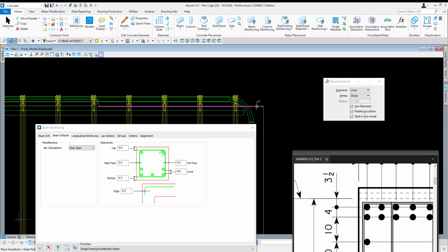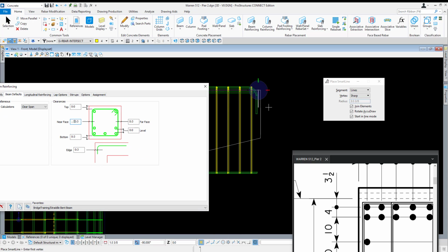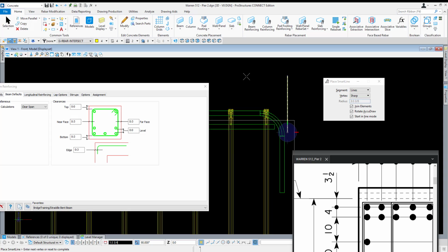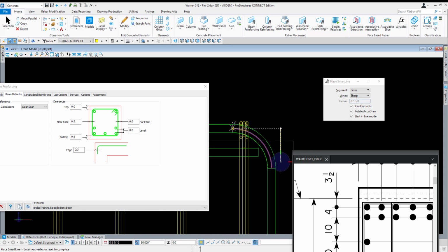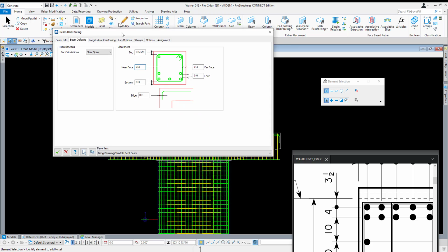I'm activating Smartline, setting my origin here, and hitting Smart Lock by hitting enter on my keyboard, and I'm going to go down 3.5 inches. Oops. Let's delete that out. When entering down into my ACS here, 3.5 inches. Click one time to begin drawing my line there, and I'm going to see, okay, looks like we're about 5 9/16 or 5.5 inches off from where we should be. So real quick, I'm going to come in here and say 5.5, hit tab, and let me see. So we should be about 3 7/16. If you really wanted it to be precise, you could shift it down to, looks like we're bouncing around a 1/16 off from a half, so that's good enough in my opinion.